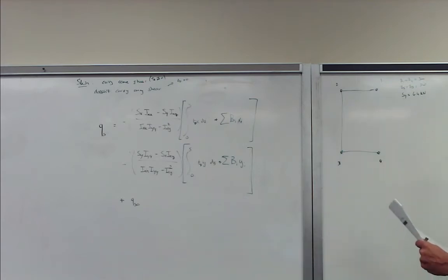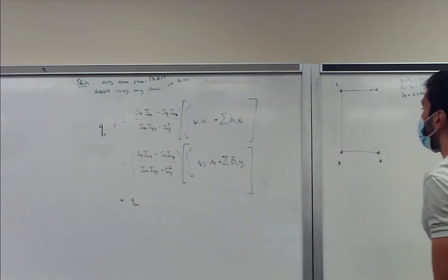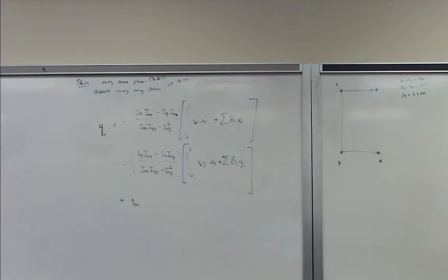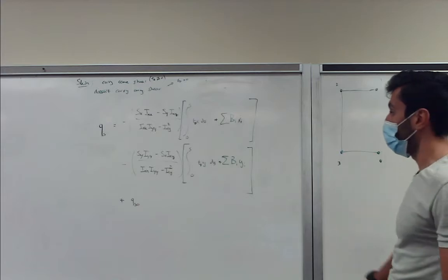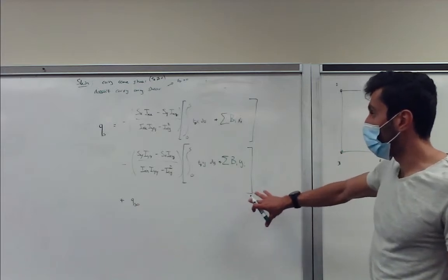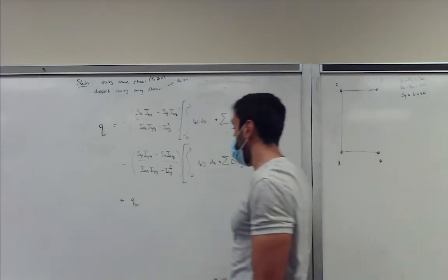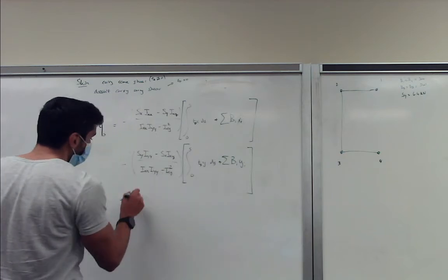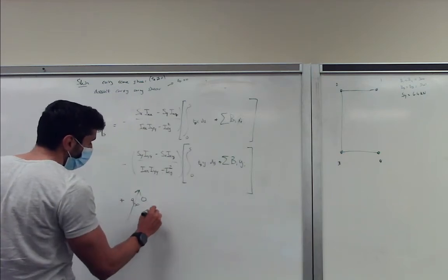And we can basically calculate again using this formula the shear flow for a boom or idealized cross section. By looking at the shear flow formula, we can immediately see that a correction shear flow is not needed because this is an open section. This part is 0.